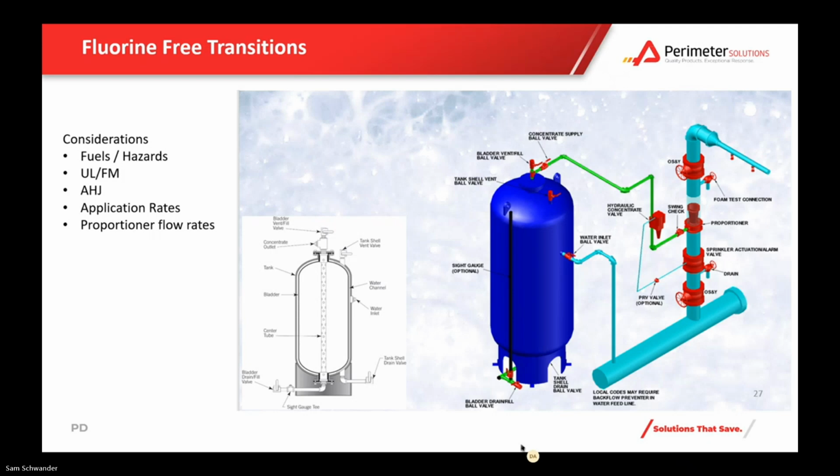The other reason being, at those low levels, those parts per trillion that we're looking for PFAS chemicals, flushing the system like that is not going to get rid of all of that old material. And once you fill it back up with a new fluorine-free product, there is a potential to contaminate the new product, right? So anything that touches raw concentrate, we definitely want to replace, right? So at a minimum, internal bladder material, these bladder tanks, concentrate piping, and ratio controllers at a minimum, right?